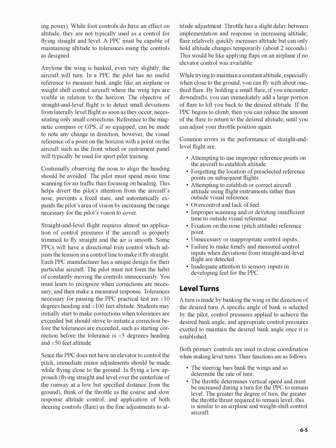Tolerances necessary for passing the PPC practical test are plus or minus 10 degrees heading and plus or minus 100 feet altitude. Students may initially start to make corrections when tolerances are exceeded but should strive to initiate a correction before the tolerances are exceeded, such as starting correction before the tolerance is plus or minus 5 degrees heading and plus or minus 50 feet altitude.